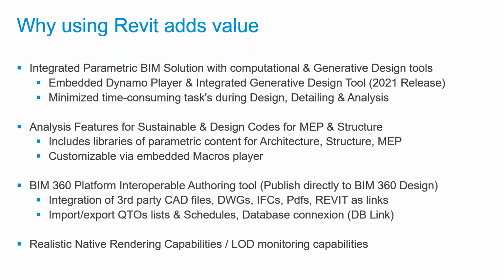So it enables you to do computational design and, more recently, generative design. It has an embedded Dynamo Player, so you can run any type of Dynamo script within Revit itself since the last two versions. And the current release, 2021, has an embedded generative design tool.